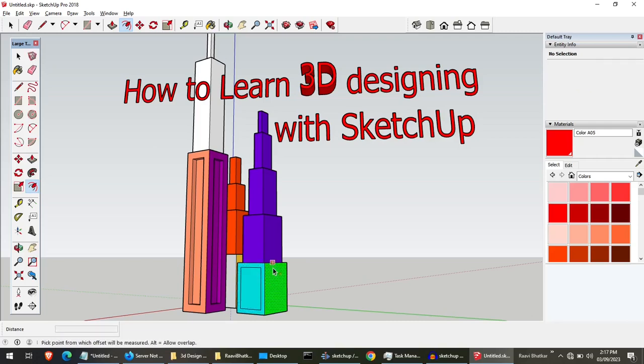First you make some offsets on each and every building. You have to move the mouse exactly on this face, not on another face and expecting to make an offset on this face. It will create the offset where you keep your mouse. And now click on the edge, and you can try.